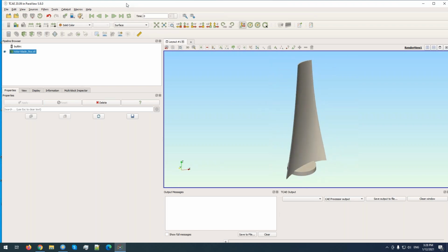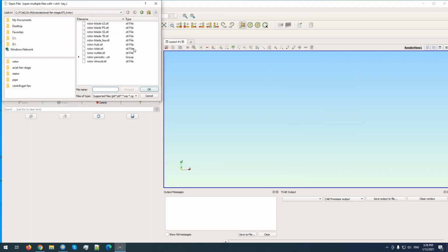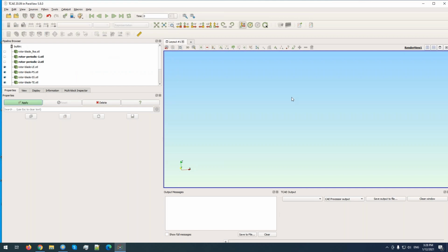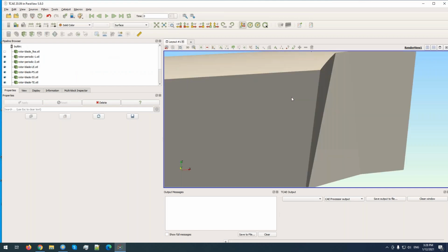Here, for example, I have clicked the geometry for FEA analysis. This is the solid of a blade which we would like to analyze in the sense of structural analysis. And for safety purposes, we need to have the closed domain where the flow is simulated.